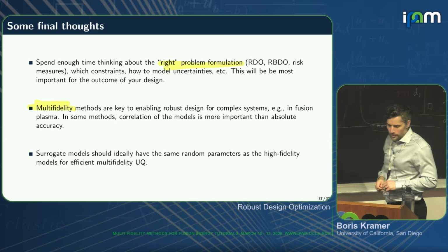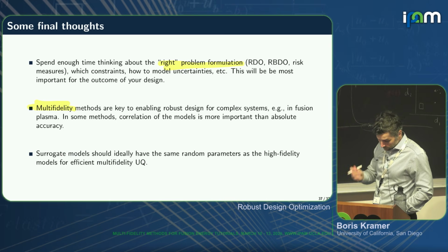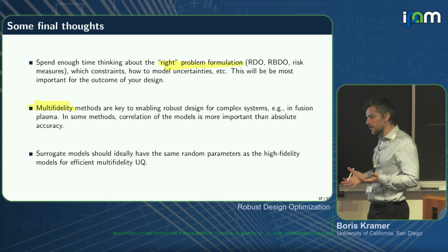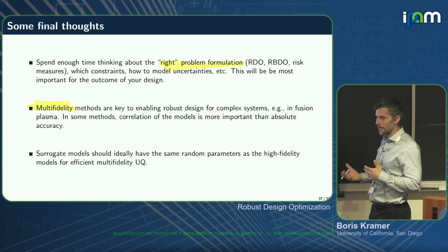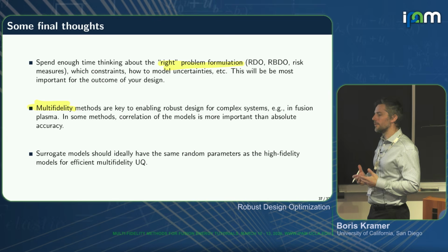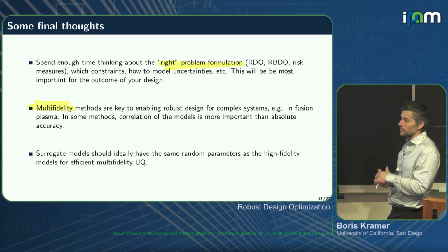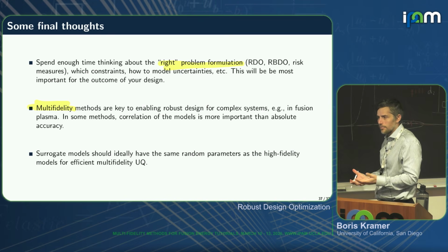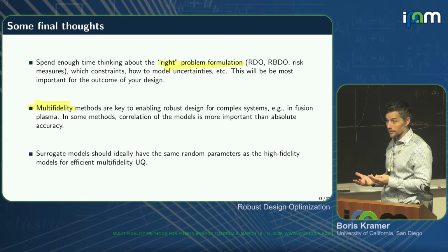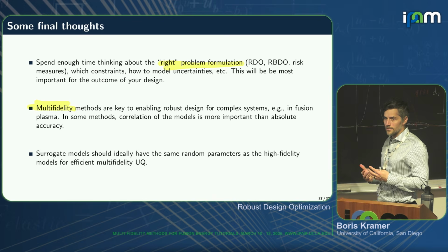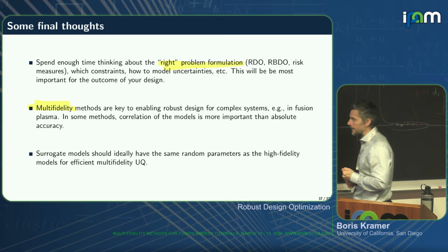Lastly, surrogate modeling, as we have mentioned in this setting: when you design surrogate models, but they're not taking the same inputs as your high fidelity models, you're having at times a problem because you're trying to sample uncertainties, but your surrogate model is not taking that uncertainty. It's not reflected in it, it's not modeled in it. So in PCEs and in GPs, we naturally do that because we start from the random variables, but if you use other surrogate models, approximations, simplifications, stuff from the textbooks, you may have to think a little bit harder how you want to use them in UQ, okay? And I think that's about it.